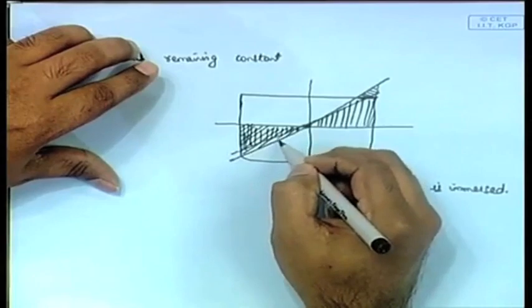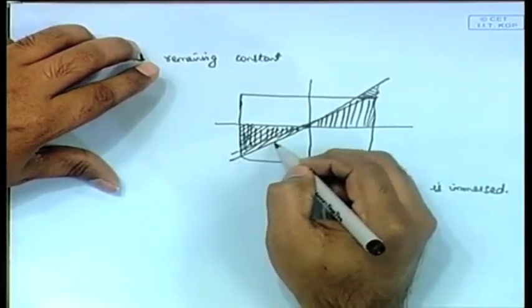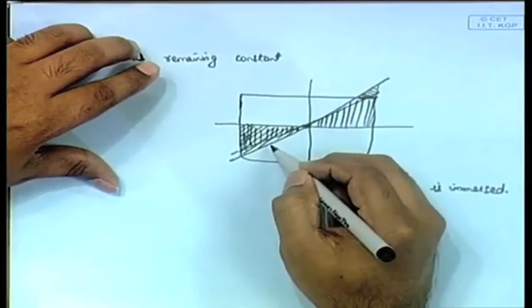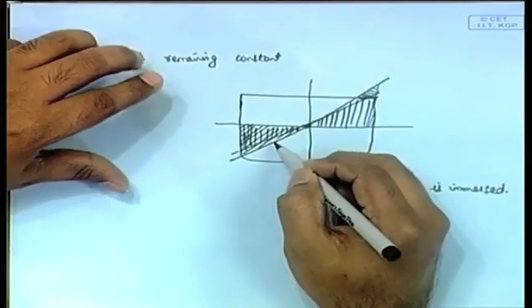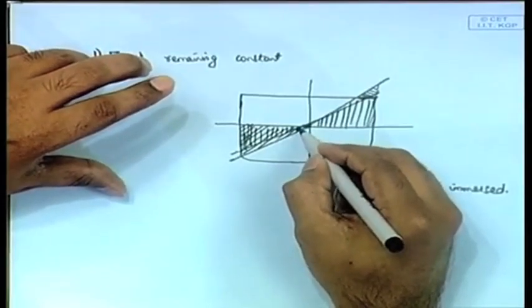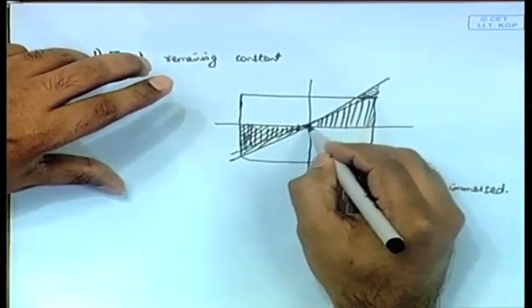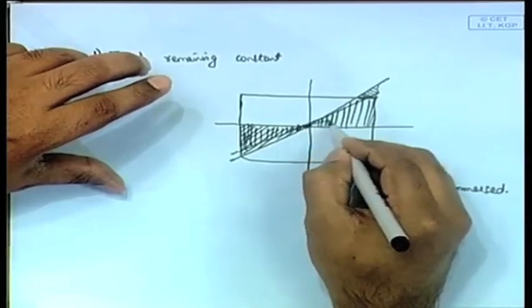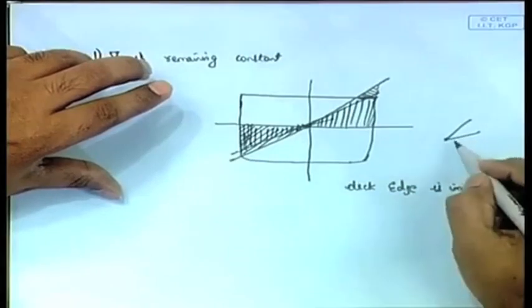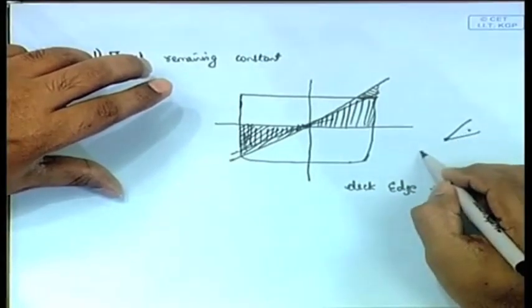There is a decrease in volume here. Now, the intersection of this line and this line is here now. Therefore, this volume actually starts from here, it opens out like this from that point. Therefore, we have an increase in volume on this side and a decrease in volume on this side, and we can keep moving that point such that we will have volume emerged and volume submerged equal.